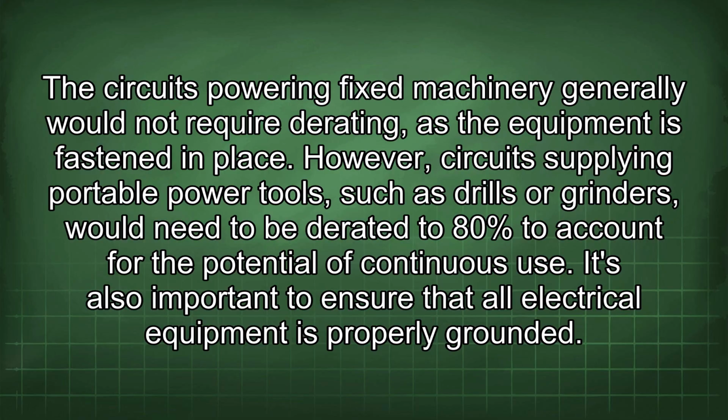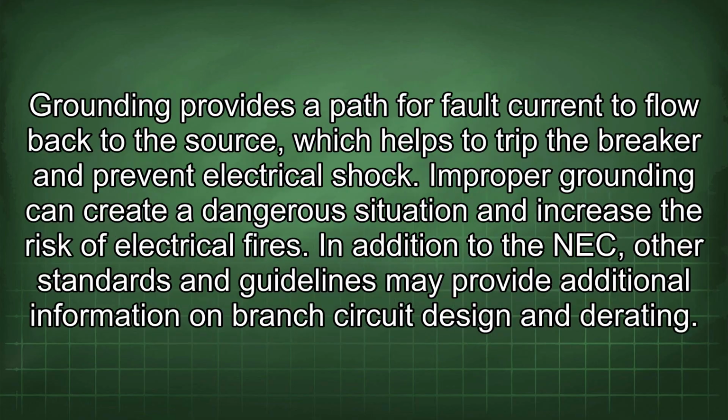It's also important to ensure that all electrical equipment is properly grounded. Grounding provides a path for fault current to flow back to the source, which helps to trip the breaker and prevent electrical shock. Improper grounding can create a dangerous situation and increase the risk of electrical fires.